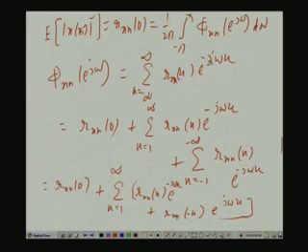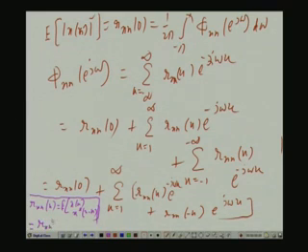Now, remember one thing, I am doing it separately here. Do you remember R_xx[k], what was it? E of x[n] x star[n minus k], right? This according to me is also R_xx star[minus k]. Why? First, what is R_xx[minus k]? You have got x star[n plus k] x[n]. And then if you take star over it, the star star cancels, and a star comes on x[n]. So, you have x[n plus k] into x star[n]. N plus k, if you call n1, it becomes x[n1] x star[n1 minus k], expected value of that, which is again R_xx[k].